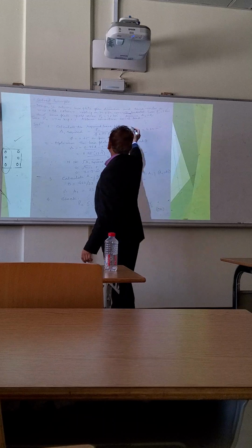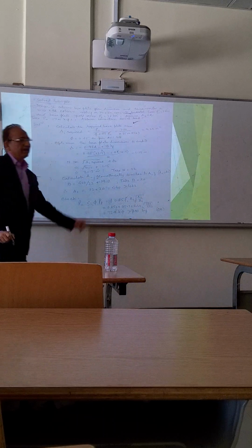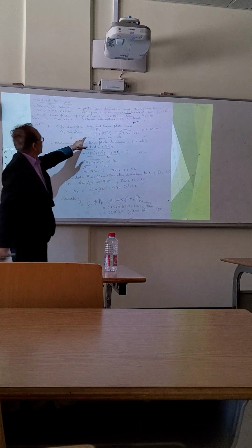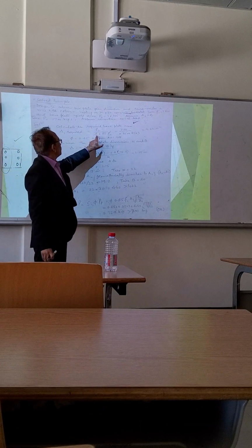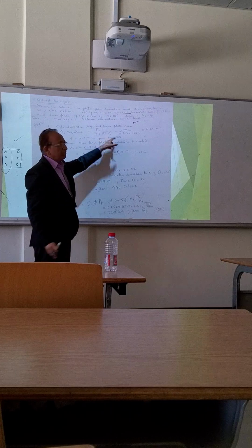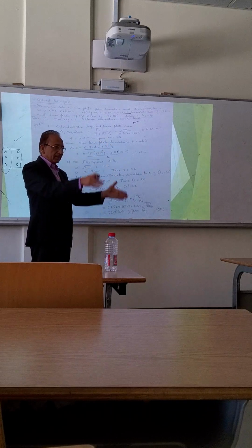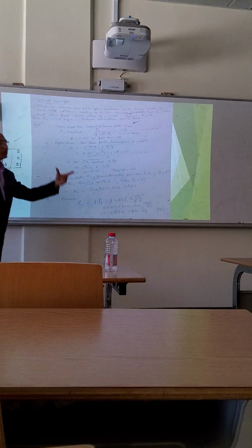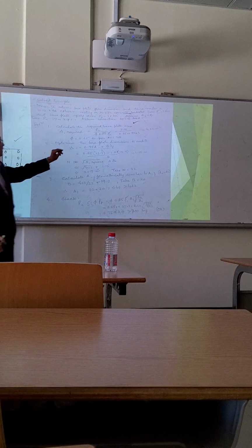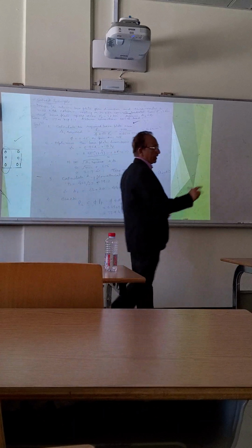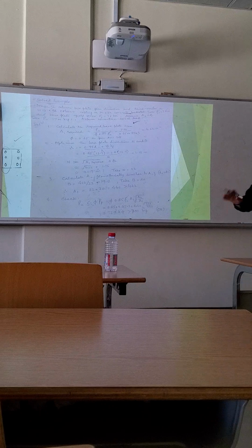So the first step is the base plate area, depending upon the load coming from the column, which is Pu upon 0.85 f'c, because there will be concrete under the plate. So it will be decided by the strength of concrete. A1 will be the area of concrete which will be compressed.